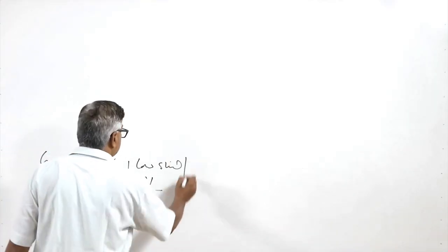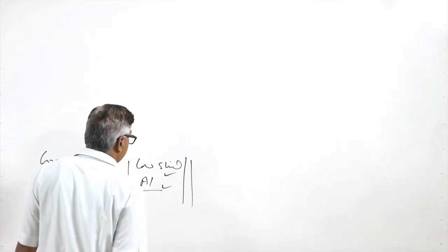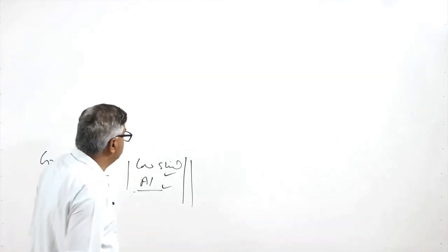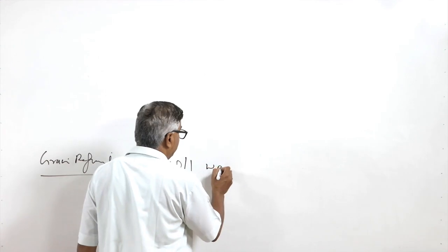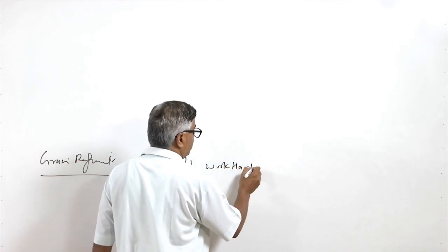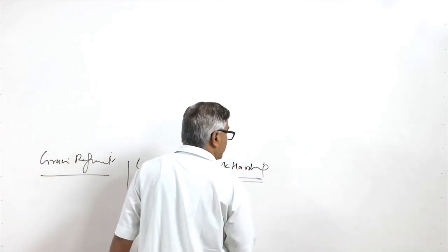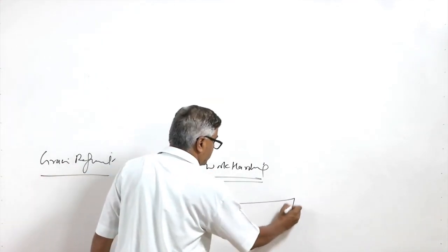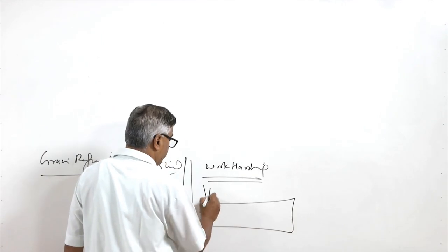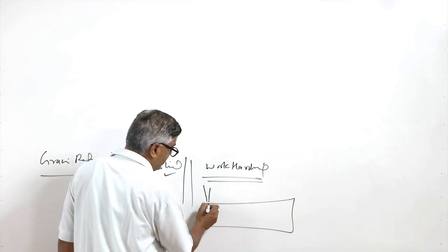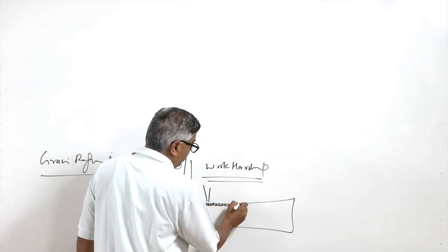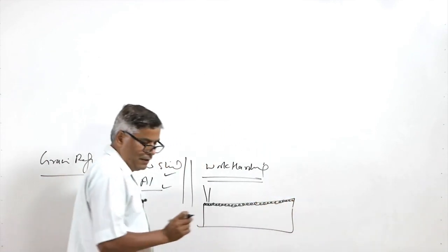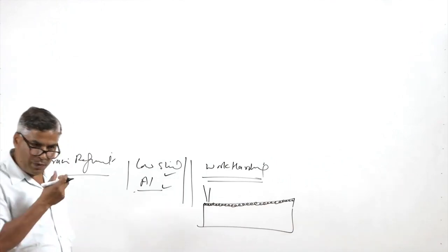But for these systems, like low carbon steel and cast aluminum alloys which are not heat treatable, work hardening methods are basically used. In addition to work hardening, just for grain refinement, what we can do is apply an intense heat source. So, the surface layer melts, followed by rapid cooling, since the layer which is being melted is very thin.